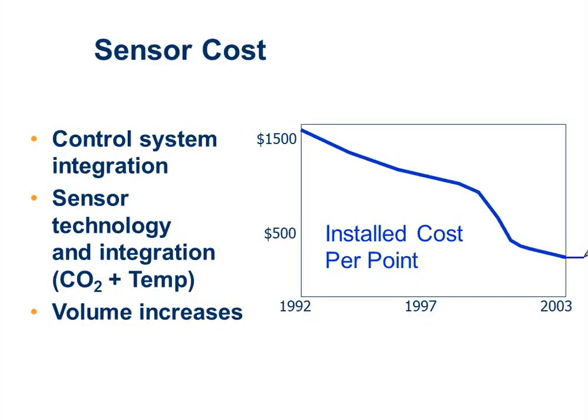In fact, sometimes it even goes up a little bit, but we're still around this same type of cost for these sensors. If you're just installing one CO2 sensor on a packaged rooftop, you're not getting that for $400 or whatever this is showing you here. That's going to be more like $600-700. But if you're doing a whole project, that's when you can get the cost down below $500. So it can be fairly cost effective if you're already doing other work in the space anyway.